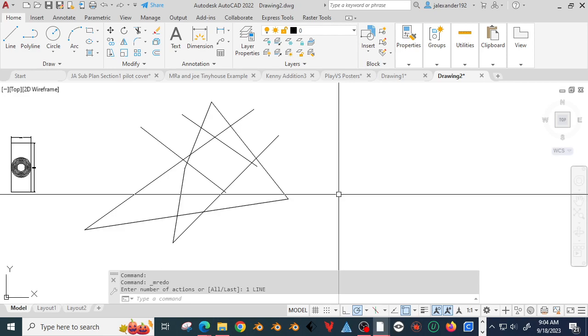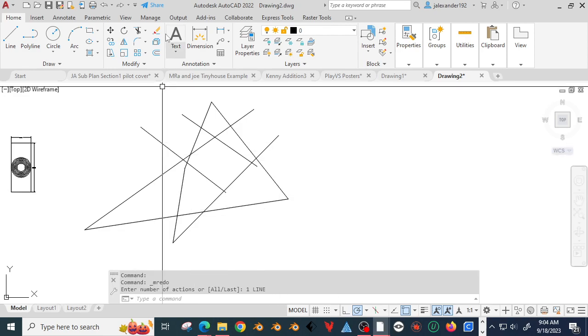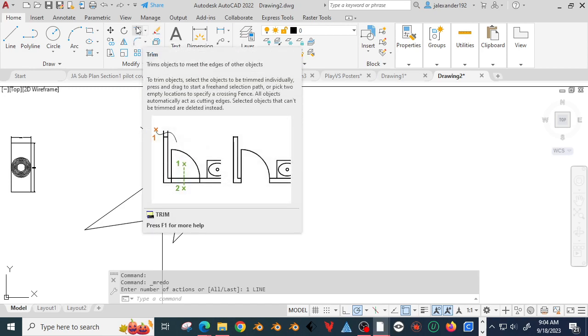Okay, this is the only other tool that you're going to use like all of the time. I saved the best for last, okay? And then I'm done, I promise. All right, this is going to be called Trim. Trim is also extend, basically. So, I could read all this, but this is going to confuse you. Let's just see how it works.